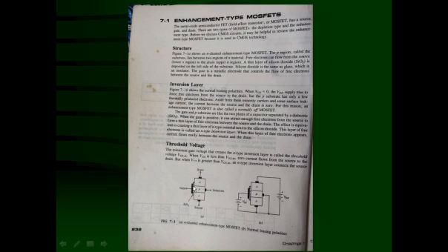Here, on the left side of the substrate, there is a thin layer of silicon dioxide, which is nothing but insulating glass, deposited, and then there is a metallic electrode which works as the gate. So, between this metallic plate and this P-type material, that is the substrate, there is an insulator. So the substrate and gate will work as a capacitor. Now, how it works and what the inversion layer is, that you have to understand.